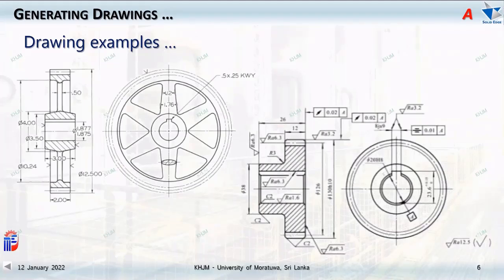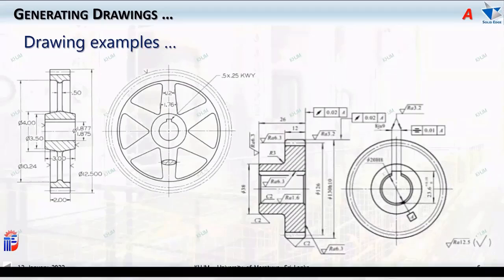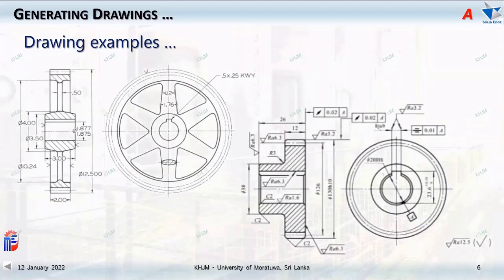And look at the one on the right hand side. There are many symbols given. What do they mean? For example, in the middle, there's a diameter of 126 or something. And immediately to the right of that, you have something like 130 H10 or something. And also 20 diameter 8 or something. That is a capital H and this is a simple H. Right? Some machining symbols are there, and the surface roughness is also given.